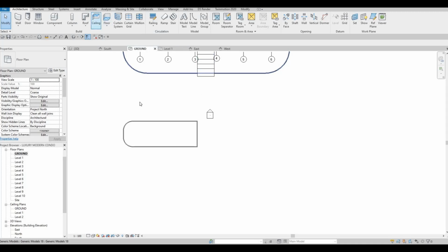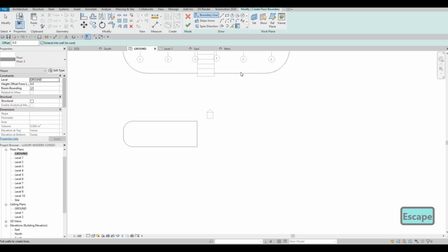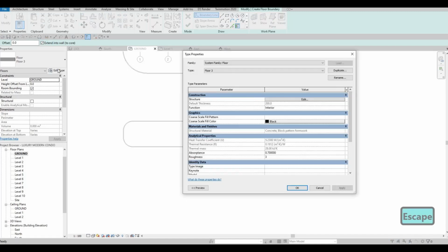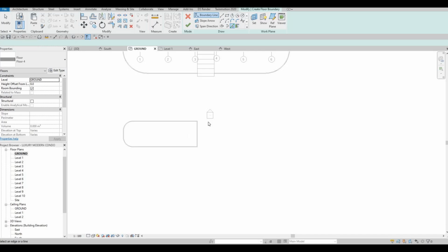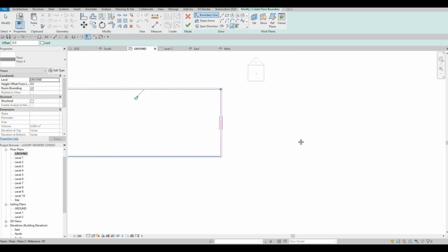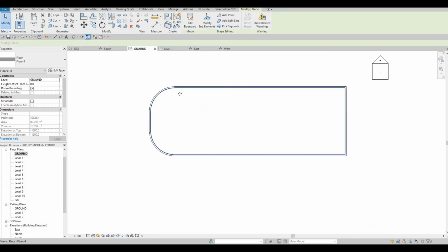So before we mirror it, what I'm gonna do is we need another floor. Edit. Not sure if floor number 3 is a grass, so no. So edit, duplicate number 4, and then here let's put grass, and then press OK, and then OK. Pick a path or pick line, and then select that, and then put 100 again.